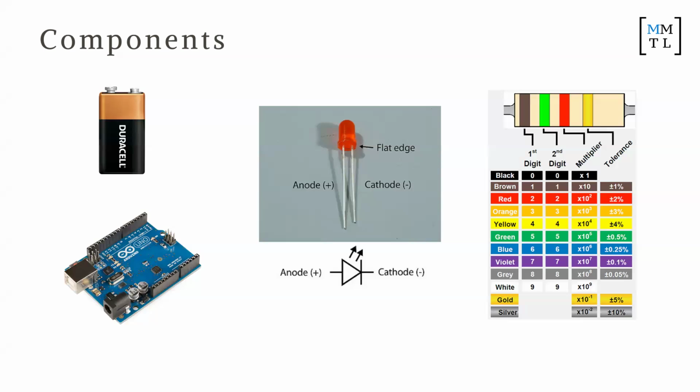If you found the 330, practice with the 1K and the 10K ohms as well. See if you can figure out which is 1K and 10K without looking at the marking. 1K would be 1, 0, and then the multiplier. You get the first 2 digits and then the multiplier. It would be brown, black, red.